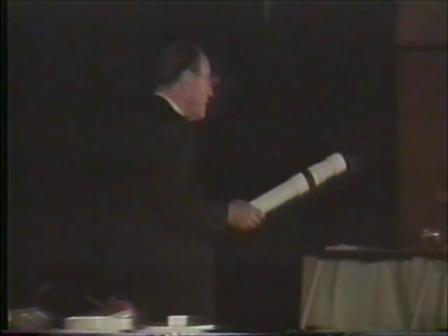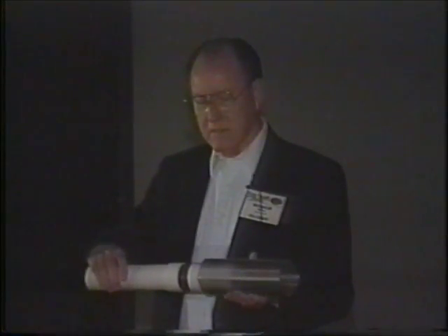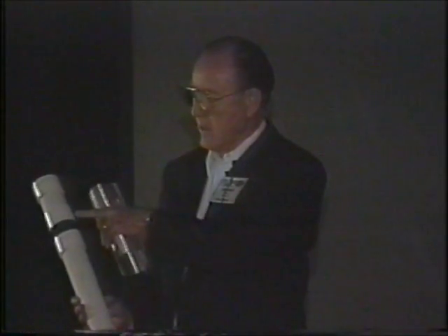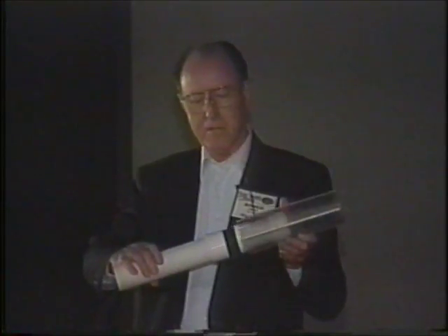Now, I'm going to show you in a little bit a slide that shows this exact same thing from 1893. It was one of the early radio devices, how they were able to tune them fairly easy. So this is your L1 coil, L2 coil, and the way we're going to do this is PVC, and I cut a collar here so that I could slide it on there and use it for a spacer and put another one there as a spacer, and the net result is that this thing fits almost perfectly. It slides in and out of this particular coil here.